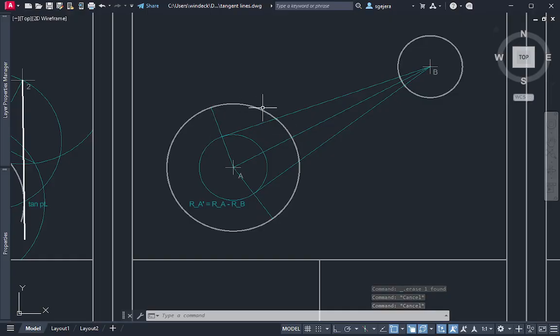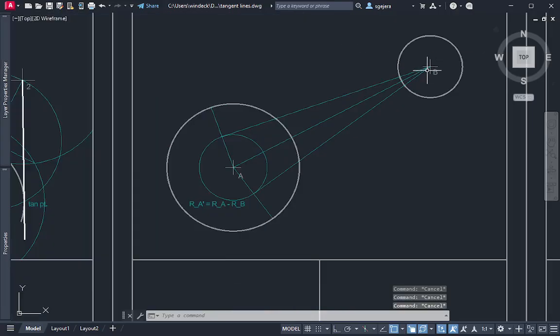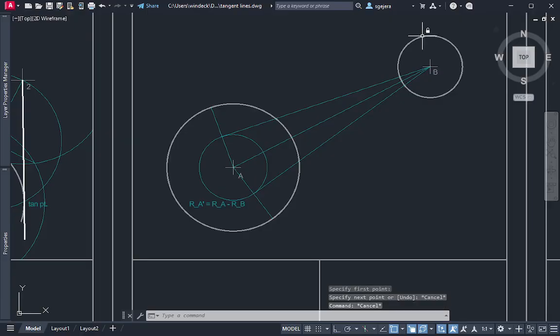So, ang gagawin nyo is, you already have this tangent point. Ang kulang nyo na lang is the tangent point here. And you can find that by creating a line from point B that's parallel to this line right here. Kung mahanap mo yung parallel line na yon, then you can find it here kung saan sila nag-meet. Yun yung tangent point. The easiest way to do it is through, hindi nga parallelogram method. The easiest way to do it is through the rectangle method.